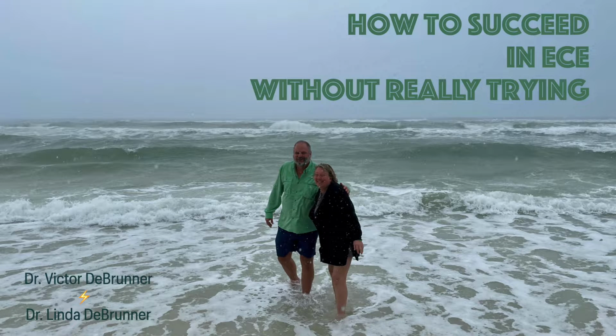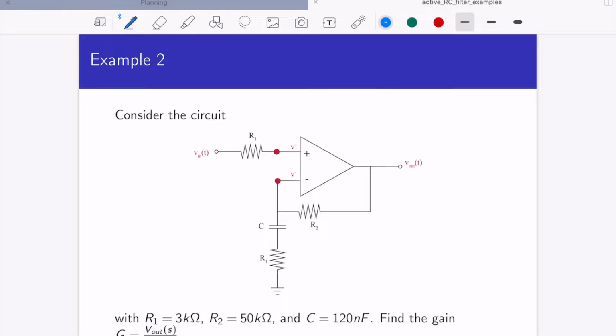I'm Dr. Linda DeBrunner, and in this video, I'm going to talk about analyzing an op-amp circuit and also talk about finding the frequency response at a particular value. This one's quite a bit different than anything else we've already seen, but we still follow our same steps. We assume that the currents going into the terminals are equal to 0. We assume that V plus and V minus are equal since we have negative feedback.